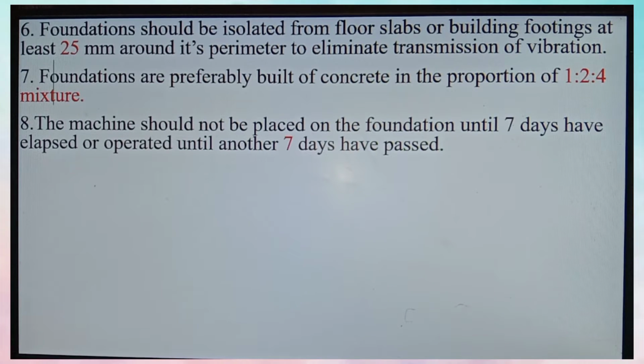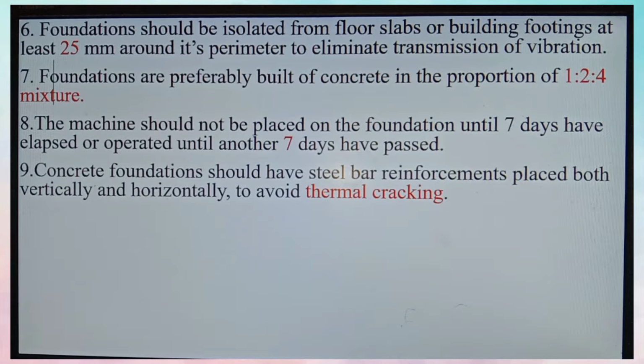Remember that, guys, for mechanical engineers who are practicing machine foundation, remember that it is 7 days. We need to put the machine only after 7 days have elapsed. Okay. So next engineering fact for considering machine foundation is that concrete foundations should have steel bar reinforcement, please, both